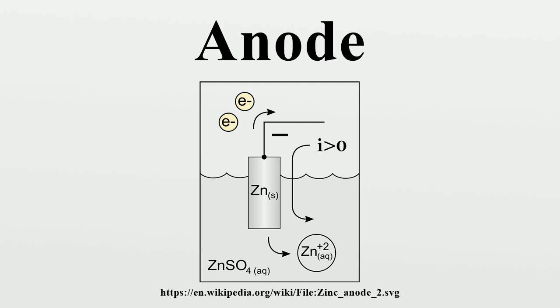Diode anode. In a semiconductor diode, the anode is the p-doped layer which initially supplies holes to the junction. In the junction region, the holes supplied by the anode combine with electrons supplied from the n-doped region, creating a depleted zone. As the p-doped layer supplies holes to the depleted region, negative dopant ions are left behind in the p-doped layer. This creates a base negative charge on the anode.